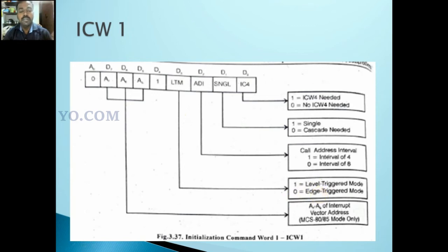Then ICW3. ICW3 is mainly used for master and slave devices. If it is a master, these 8 bits are mainly for interrupt request inputs with a slave.